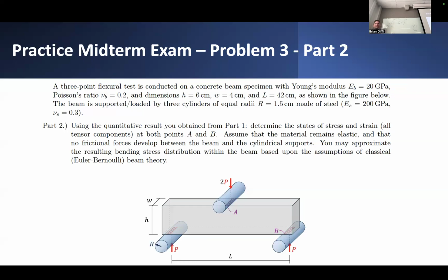So really these components of traction, shear traction or shear stress, in this case sigma y in the x direction and sigma y in the z direction, are both equal to zero. Through symmetry arguments, you can also rationalize that the component of sigma xy stress on the x face acting in the y direction is also equal to zero, because we say that sigma xy is equal to sigma yx through basically moment equilibrium. So we can hammer down those different components of traction.